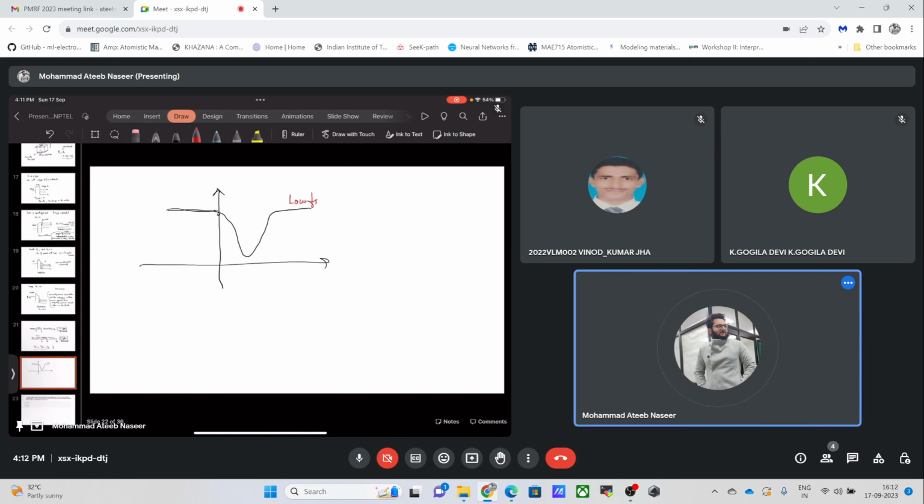Okay, this is for high frequency. So this is capacitance, this is voltage, and the substrate is p type. This is all related to the biasing conditions that we saw earlier. We said that in the accumulation region, we will have a large or negative bias applied.